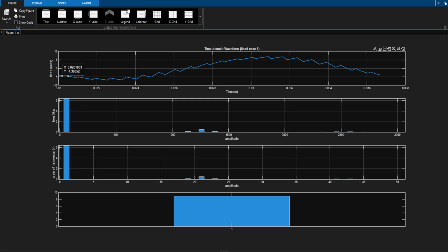Important here, since we're not using the FFT of the signals, but the manual, so to speak, classical way of Fourier analysis to find out AN and BN, we have to provide one specific time period, which is shown here in the time domain, the first window of the plot, and then we go for the coefficients to find out the different harmonic spectrum.